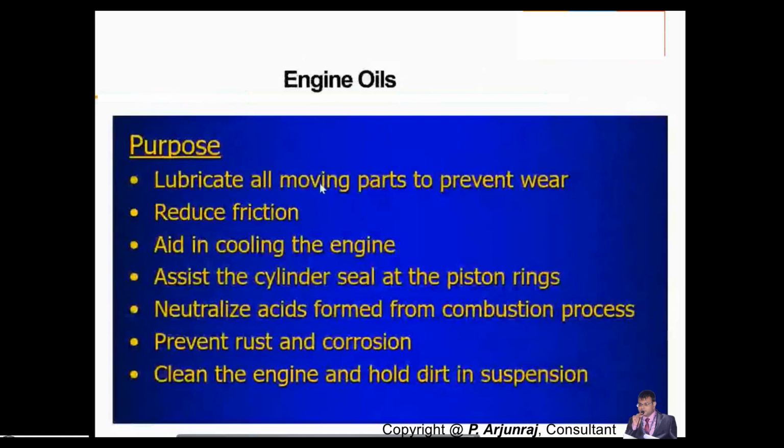The purpose of engine oil is that it will lubricate all moving parts, basically to prevent wear and reduce friction. It helps in cooling the engine. It assists the cylinder seal at the piston rings. It also neutralizes the acids formed from the combustion process. It prevents rust and corrosion. It also cleans the engine and holds dirt in suspension as well.